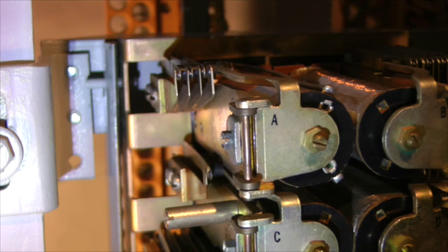If the A relay winding was de-energized by the earlier release of the G10 subgroup relay, the A relay will now finish its slow release process. If the A relay was de-energized by the operation of the D relay, it will now begin its slow release process. In either case, the net result is that the A relay releases.